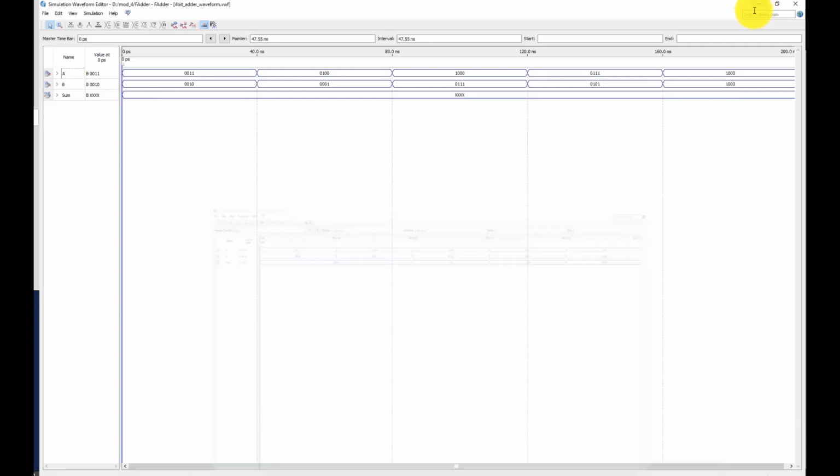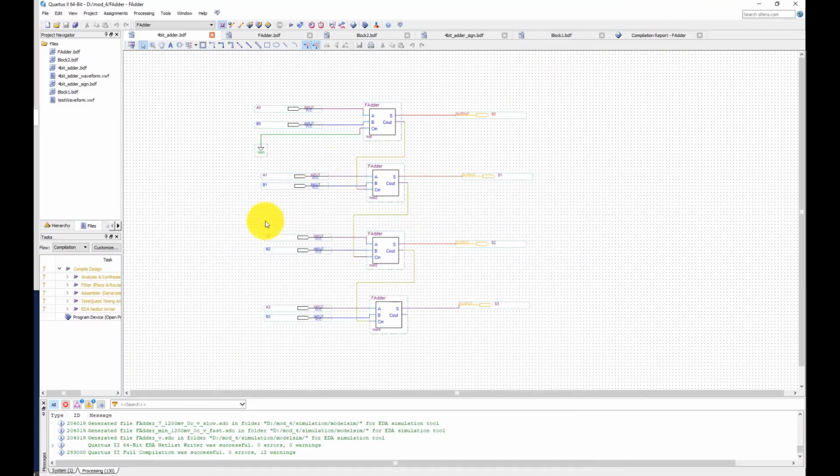Okay, what we can do to solve this issue is go back to our circuit here, and we can create a block diagram from this 4-bit parallel adder to do 8-bit additions. But before doing so, we have to make sure that we have an output for the last carry out, because I want to connect the last carry out to what?